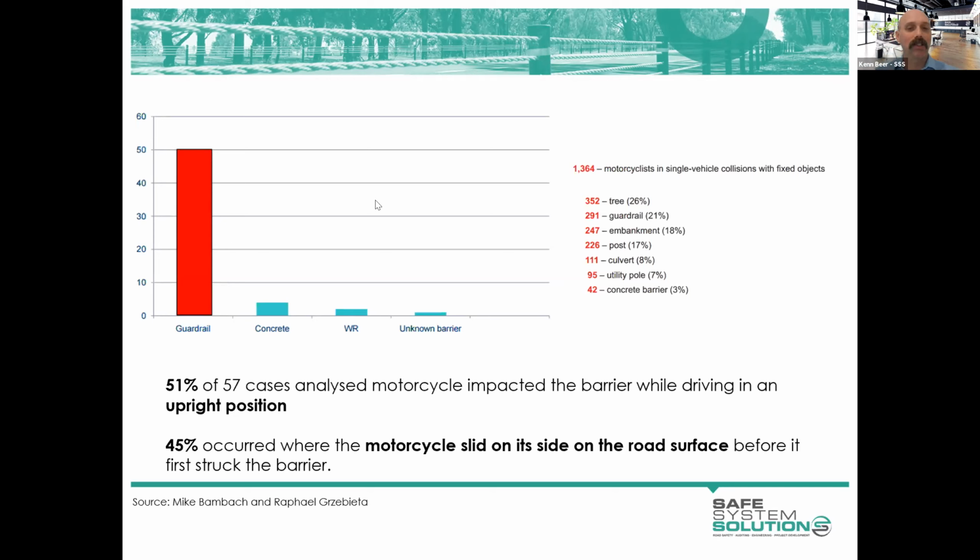And you cannot install a wire rope system, because you'll remember that one of the requirements is a minimum 200 meter radius, because it's in tension. It'll pop into the middle of the road if you tension it up on a sharp curve. So on those routes, it's always going to be guardrail.